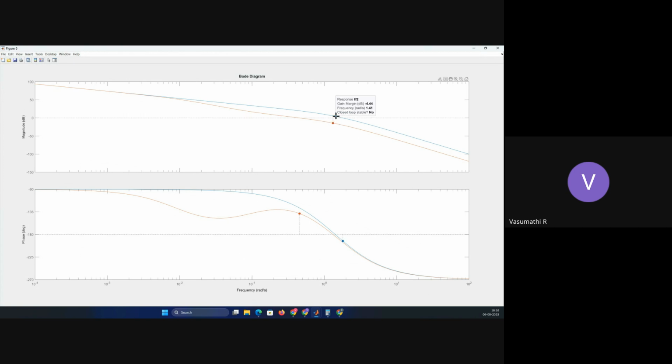Right. The previous gain margin is minus 4.4. Now the gain margin is 14.3. So we shifted the Bode plot towards left and added the phase. And the previous phase margin is minus 13. Now the phase margin becomes 41. Exactly a little bit above 40, but that's enough. No need to adjust anything yet. Right. Now we have satisfied all the requirements of the system.